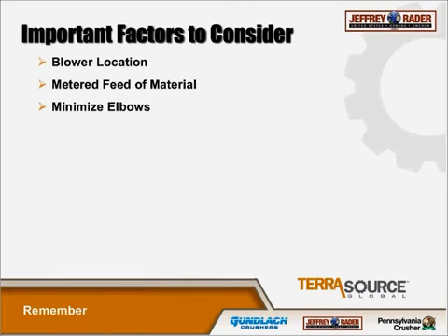It's best to try and minimize the number of elbows in the system. It's pretty simple. Fewer pressure losses are going to lead to lower horsepower requirements, save more money over the long term.